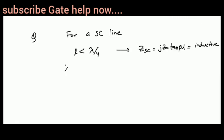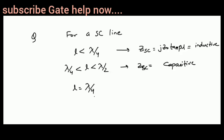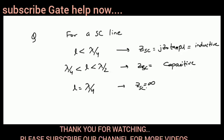For lambda by 4 less than L less than lambda by 2, ZSC will be negative, minus j Z naught. So ZSC will be capacitive, and therefore you can use this as a capacitor. Then for L equal to lambda by 4, the impedance ZSC is infinity. And for L equal to lambda by 2, ZSC is 0.